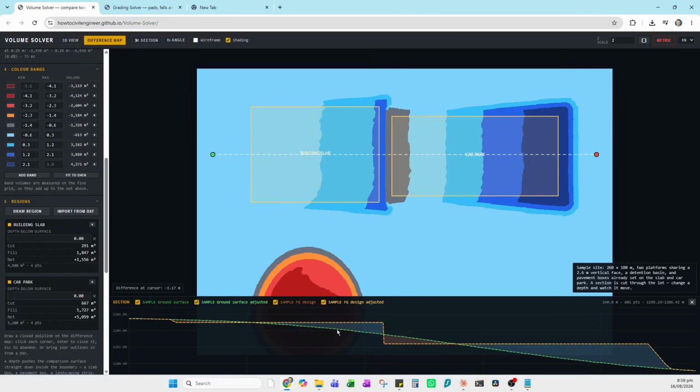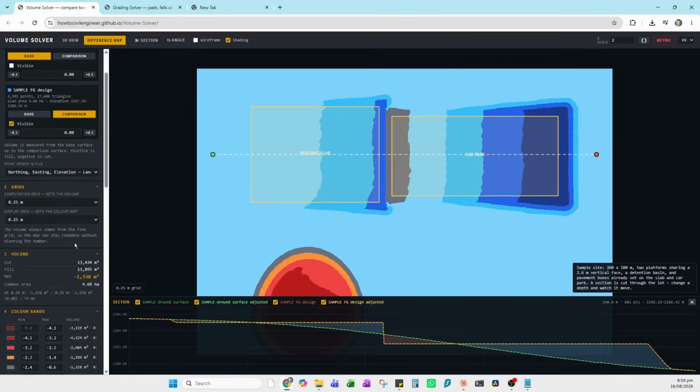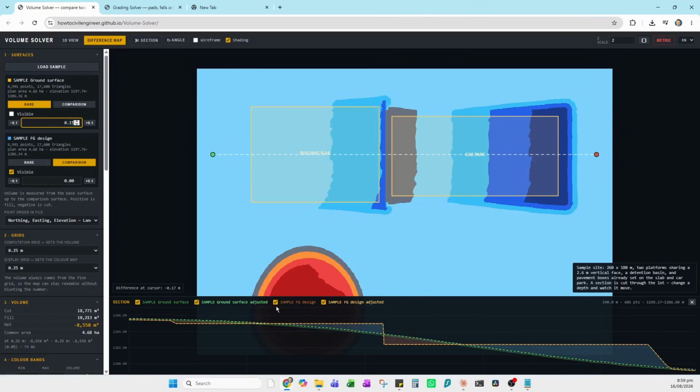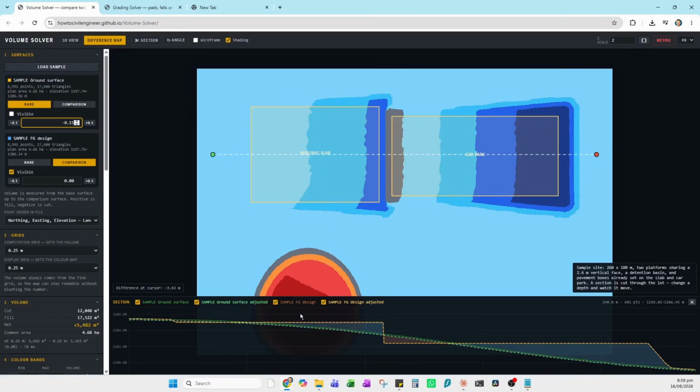And so now the comparison is just the sample ground surface and existing ground surface. And then you can see this kind of blue area is what's been calculated, or brown area. Typically we don't calculate from that, so we'd have to subtract down maybe topsoil 150 mil, say. That brings that down, and that's gone up. There's a negative value on there. And that's how that is.